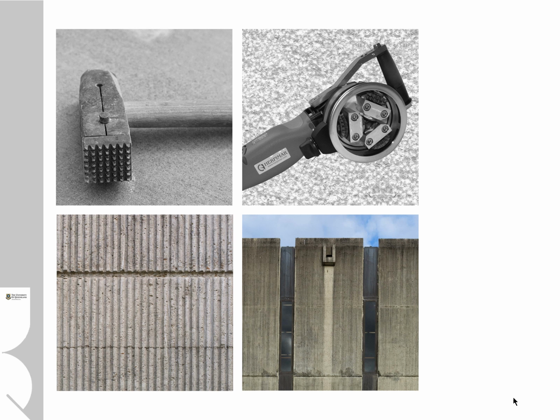Now, bush hammering is quite common in stone masonry. You can see on the top left-hand corner is a hand bush hammer, and on the top right is a mechanical version that's used in concrete work. So basically, the bush hammer scabbles the surface and roughens it all up, and if you accept that rough surface, it blends out any of the imperfection in the surface of the concrete.